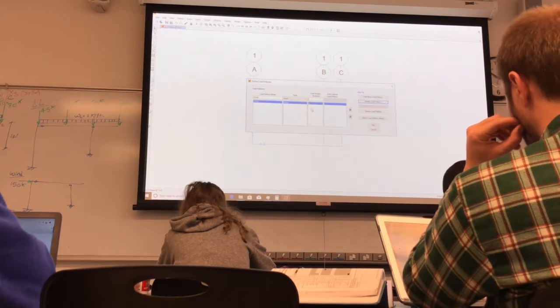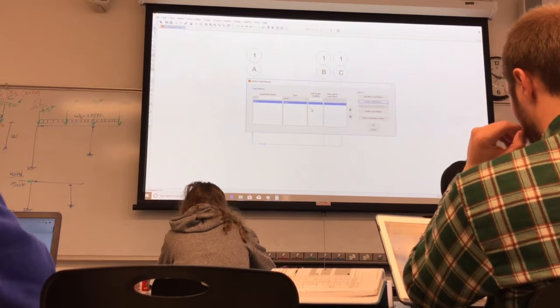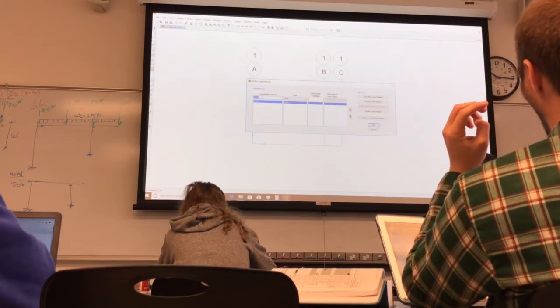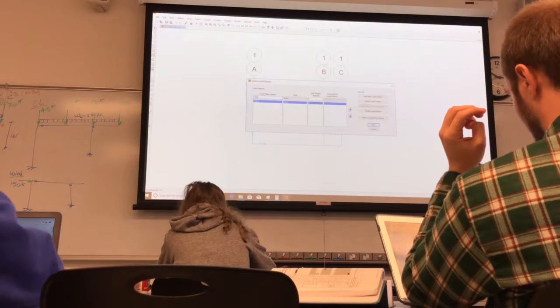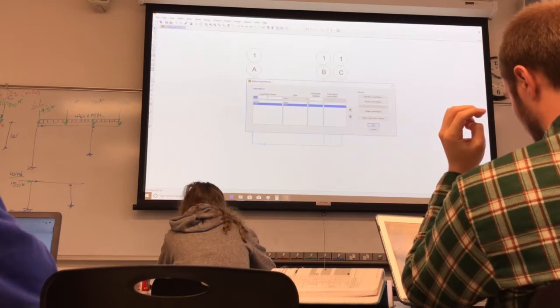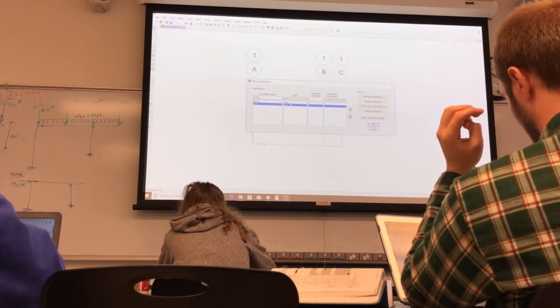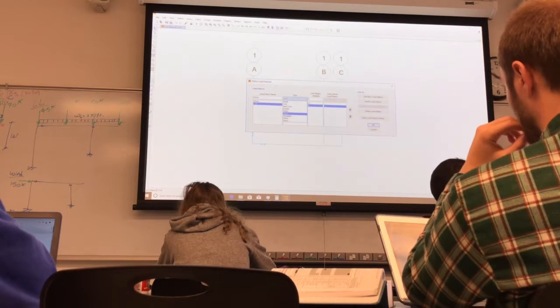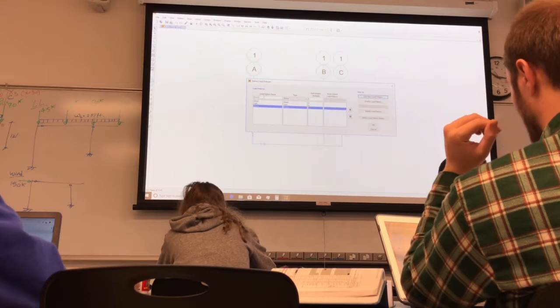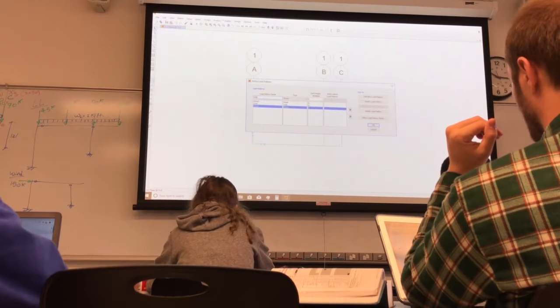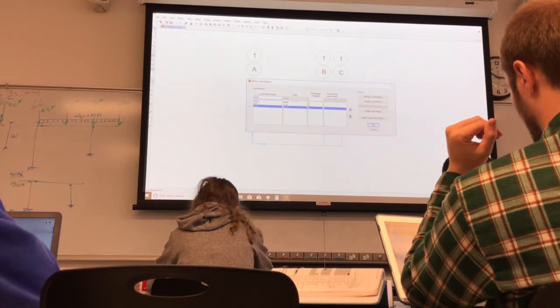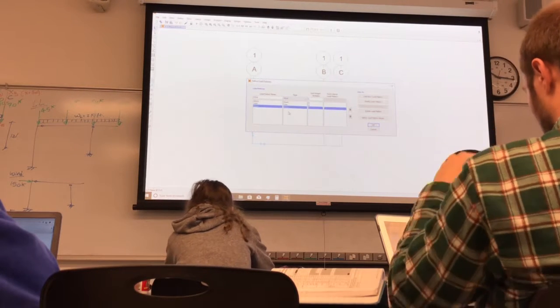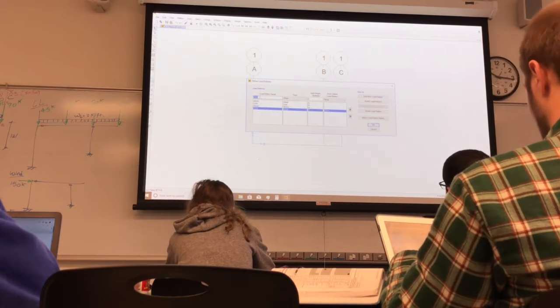So I'm not putting any loads now, I'm just defining the types of loads I have. So I have dead, and then I have a live load. I'm going to put live, and the type is live, and then add a new load pattern. Then I have snow load, and the type here is snow, so I select snow and add. Then I have wind, and you have the wind option, and I have an earthquake. I just call it EQ, and here it's a quake load, and then you add.